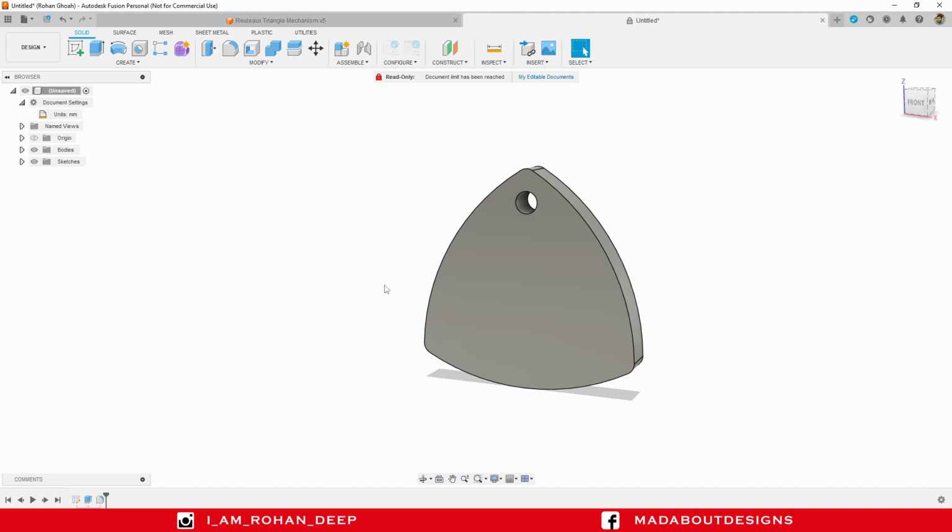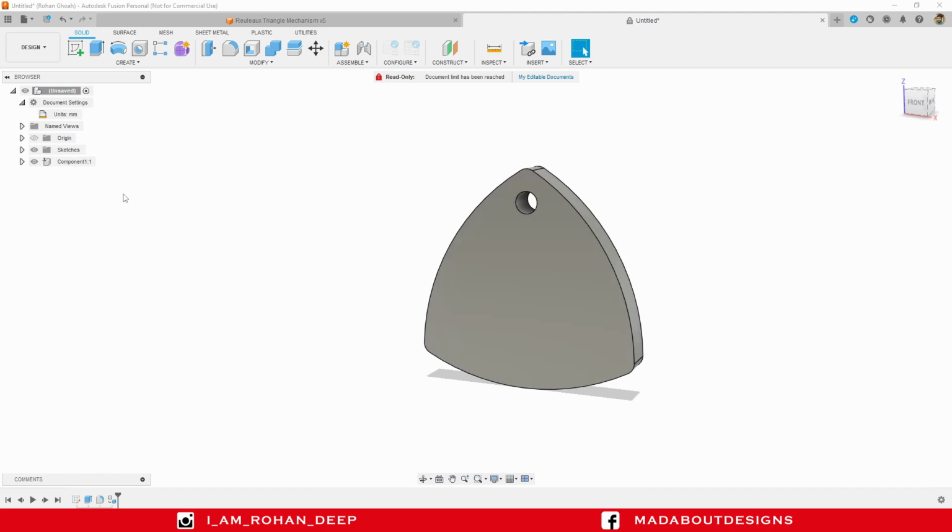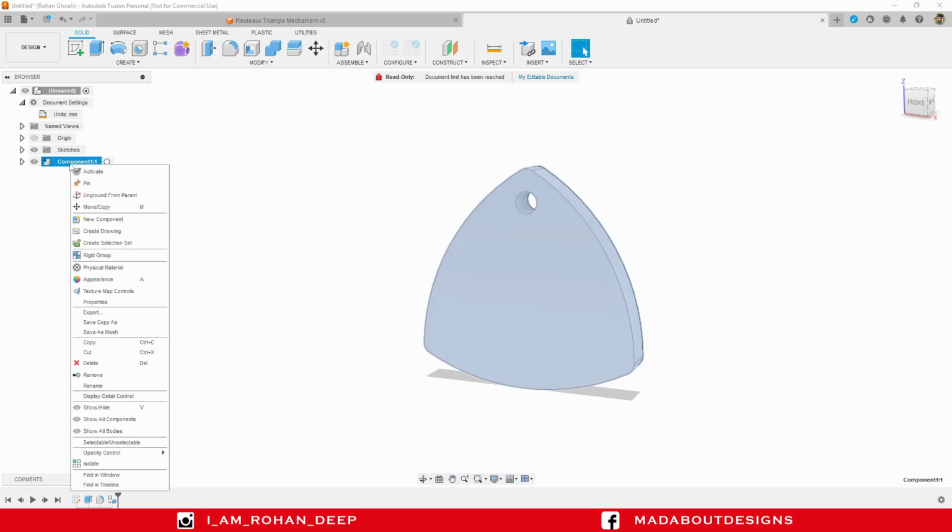Now, for the assembly, I need to convert this body into a component. To do so, go back to Bodies. Here is our Body 1. Right click on this and create components from bodies. So the body will be converted into a component. If we click on the drop down menu, here you can see Bodies and Body 1. Let's rename Component 1 as Reuleaux triangle.